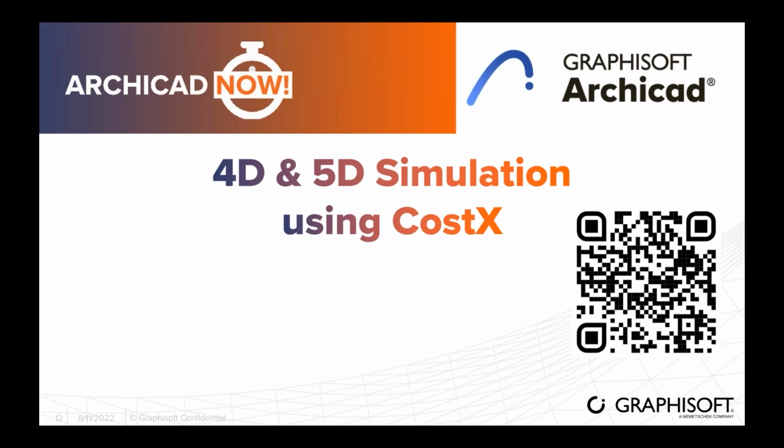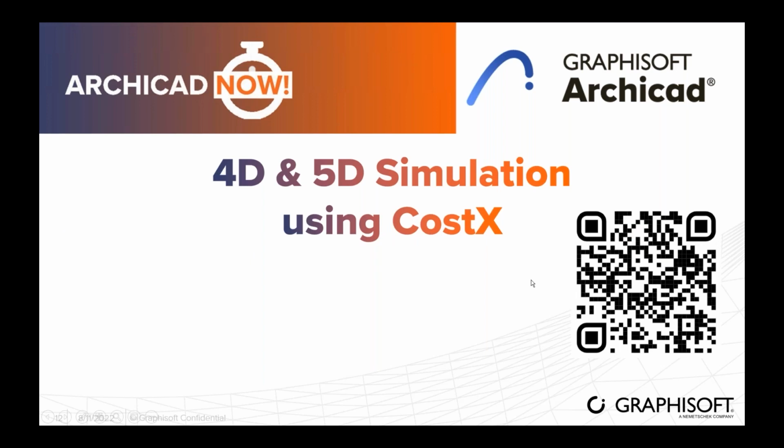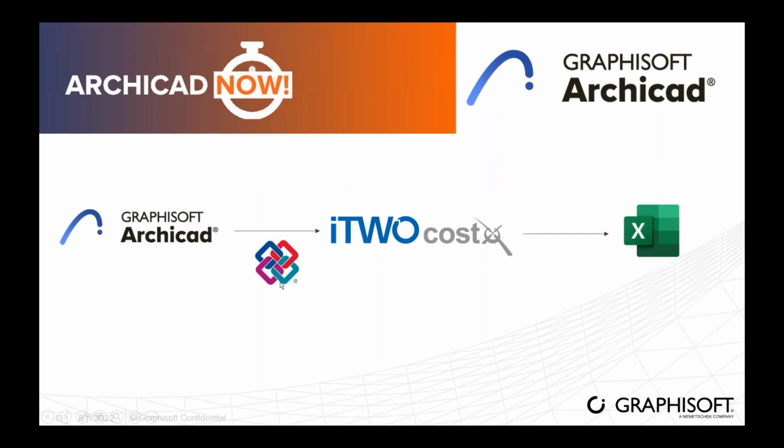So the next is CostX. You can create 5D cost estimation using CostX. So here is a video where you can watch more information about CostX. Again, it's going to be using the IFC file format. So you can export the Archicad model in IFC file format, and then you can import it inside CostX to do the cost estimation, and then it can be exported in an Excel file format. Okay, so I'm not going to show this again because of the time constraint.